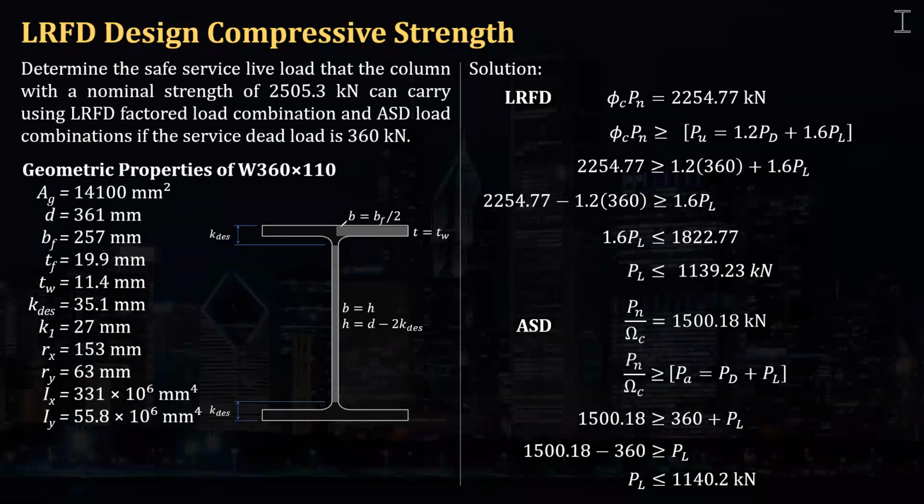Suppose I'm going to extend this, let's say the width of the flange is like this. Draw first. So this is the width of the flange. Then as you can see, it would probably buckle, local buckling. That is local buckling, before it will fail in general buckling. So with that, it would be including reduction factor Q in calculating for the nominal strength. Okay? So that would be in the future video.